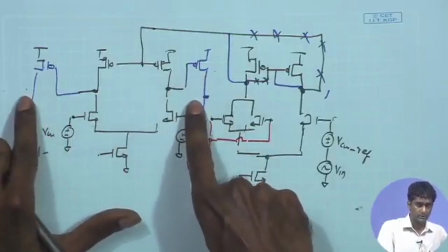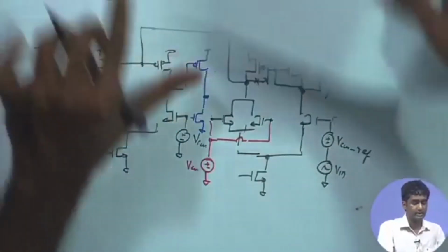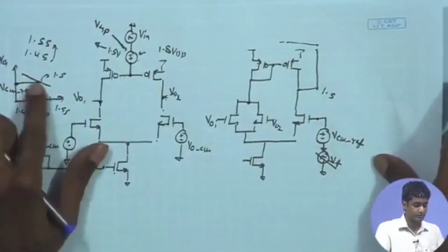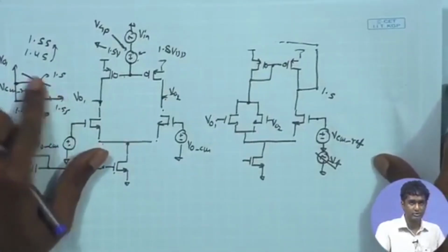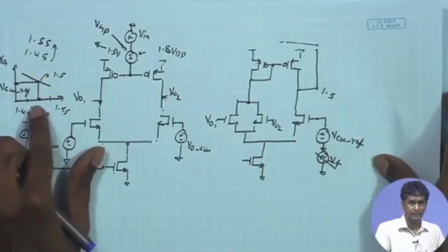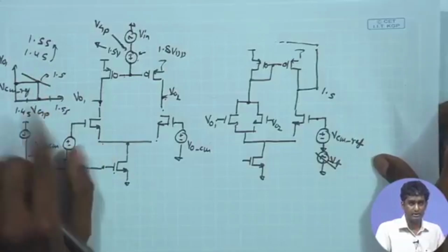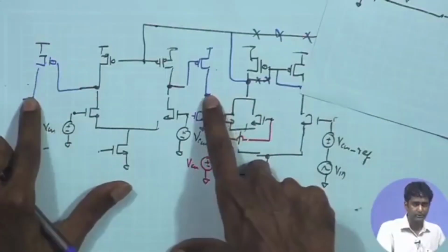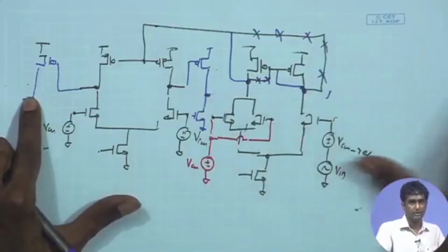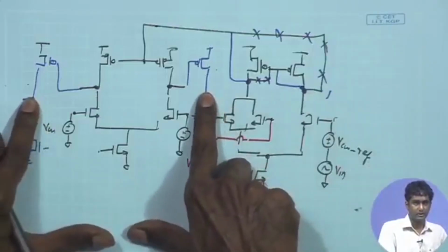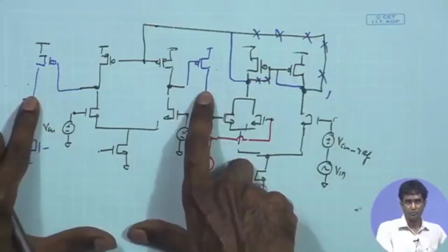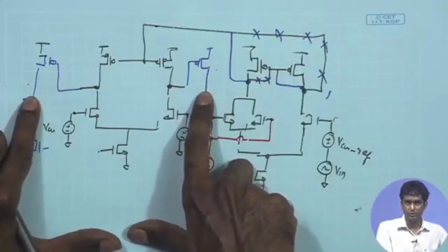Therefore the sweeping scheme that I discussed becomes all the more important, because you need to precisely locate which point you want to have as the DC bias, so that the output DC levels over here obtained for the open loop operation are very close to the common mode voltage that was obtained using closed loop.